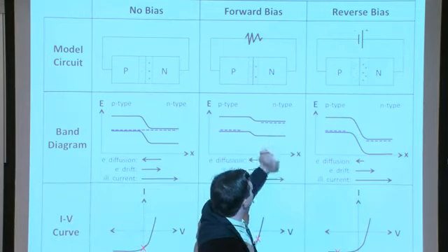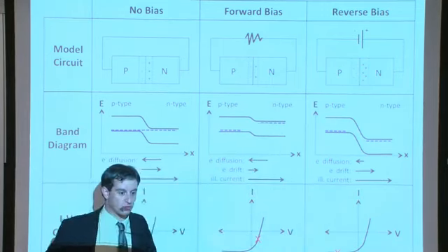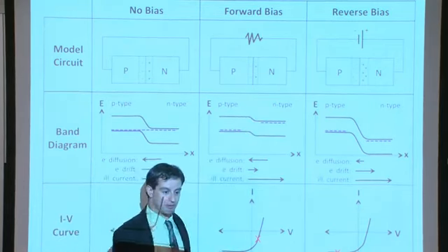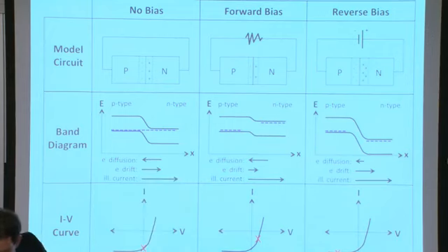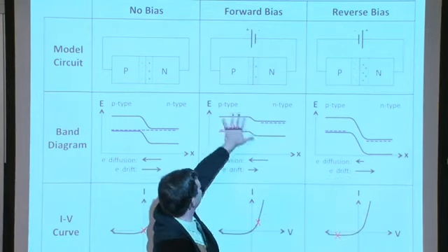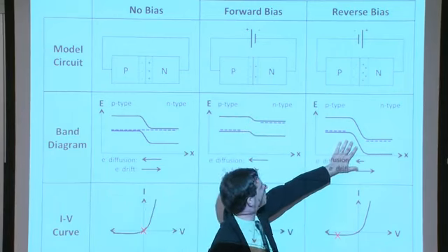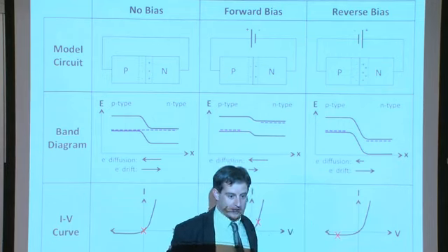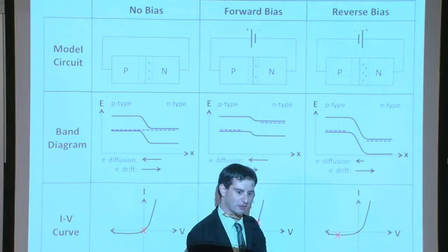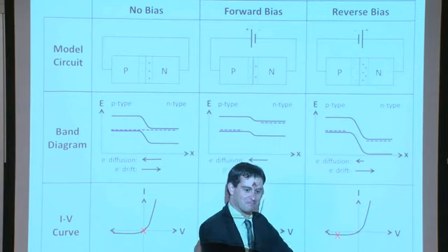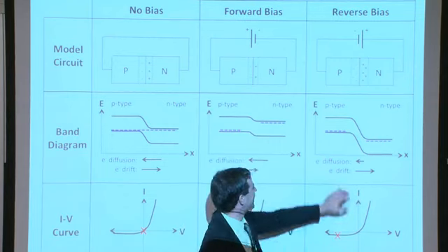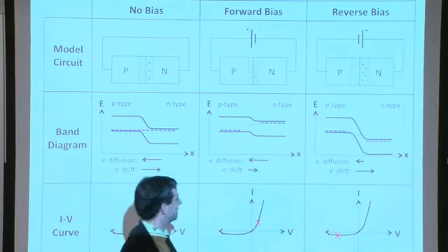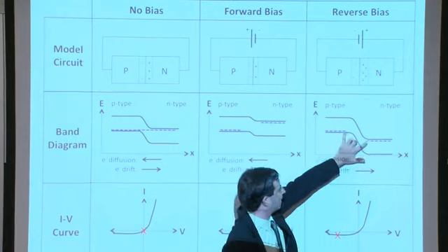What you could do, though, is have a bunch of solar cells connected in series with this one that are producing forward power. You could shade this device, and then power could be flowing backward through it. In other words, it could be in the dark, and you could be in a reverse bias condition just because of the way the other solar cells around it are behaving. If you have a shaded solar cell in a module, for example, imagine a seagull lands and covers up one of the cells. That will be under reverse bias, and that could present problems if the solar cell can't withstand the reverse bias.